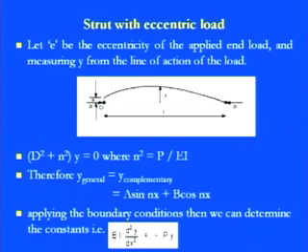If we want to write it in the derivational way, we have D square plus n square into y equals 0. Here D square is nothing but d square divided by dx square, and n square, as usual, is P over EI. So we have the second order equation, and obviously we have the generalized solution. In that we have the complementary function. If you want to calculate the complementary function, the same procedure is there, a sin x plus b cos x. Since it is flowing with n, we have a sin nx plus b cos nx as the generalized solution.